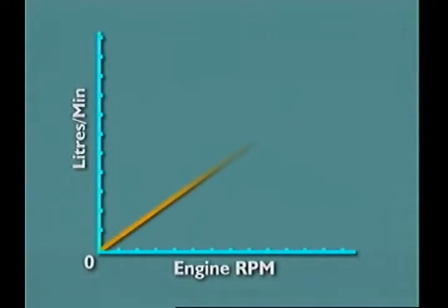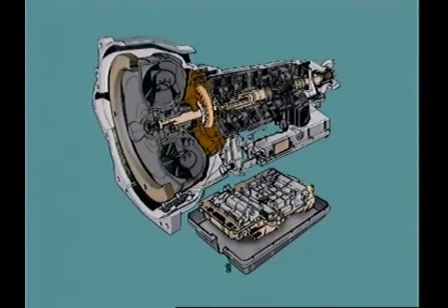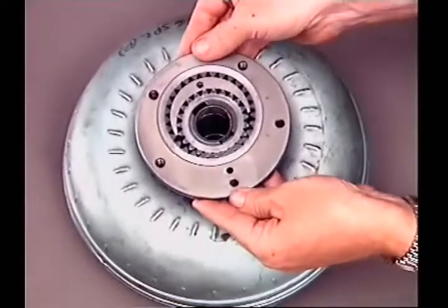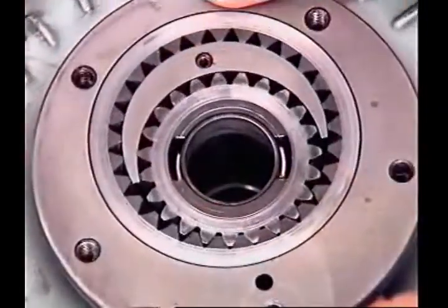Pump output always exceeds normal operating demands, so pressures are controlled by regulating valves. Excess fluid returns to the pump inlet or is dumped into the oil pan, where it can reach the pump intake strainer. Crescent-type pumps are commonly used in automatic transmissions.